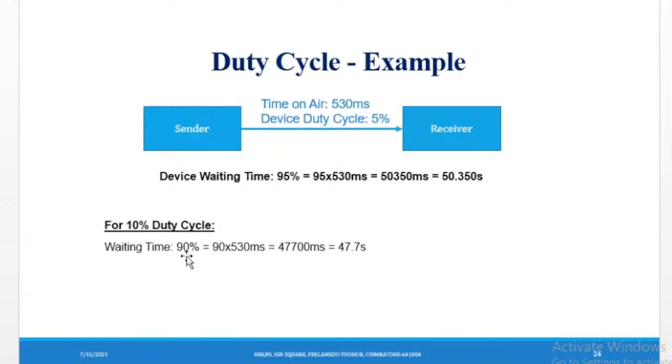Okay. So for uplink and downlink, if the duty cycle takes 10% of the time on the node side itself, then 10% is node processing time and 90% is air time. This is the entire duty cycle from node till network server. The node will take 5%, and the receiver will take 5%, totally 10%, and 90% is your air time. Likewise, I can calculate the entire duty cycle from node till gateway.